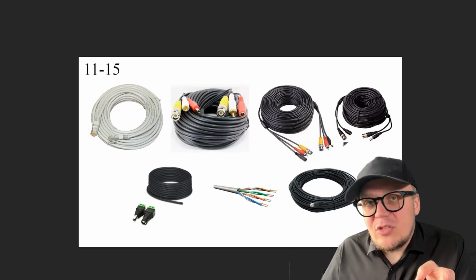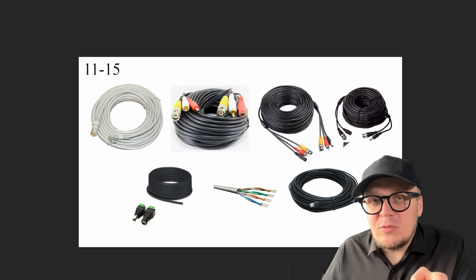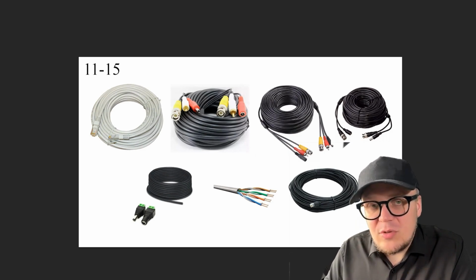Another standard recommendation from electricians. Ideally, it is necessary to separate the power cable from the low voltage cable, meaning they should not be run through the same box, they need to be routed separately.